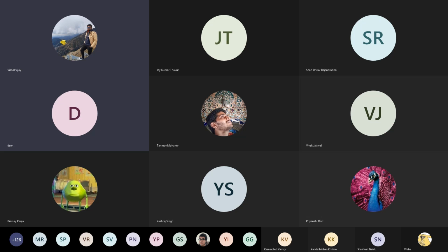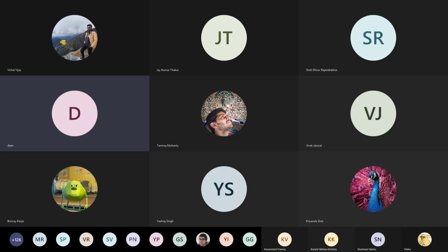Whoever asked this question, so if you divide by that, what is happening? I didn't notice who asked the question. Somebody asked this question, right? When you're saying FC is 1 by 2 pi RC, and if you substitute that FC in place of F in the phase, it becomes what? Tan inverse of F by FC. Yeah? F by FC.